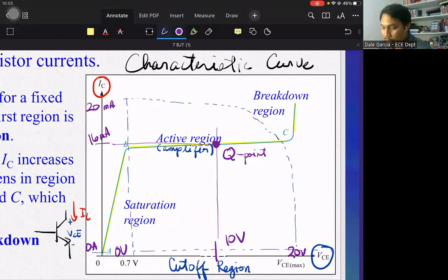The opposite of that is a very large voltage, let's say for example 19 volts, but close to zero current. Almost no current passing through it. So it is in the cut-off region. Easy to remember: high voltage and no current. When we say no current, it's as if our device is turned off. So it is in the cut-off region.